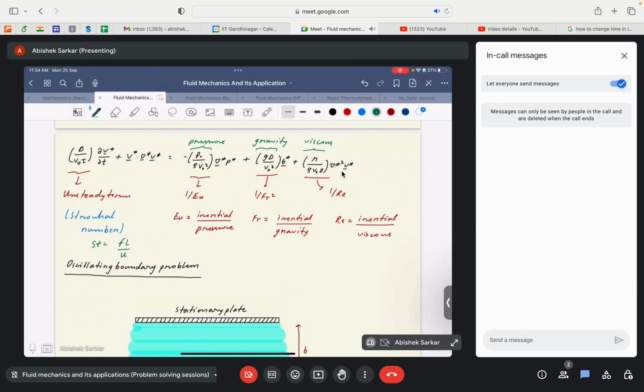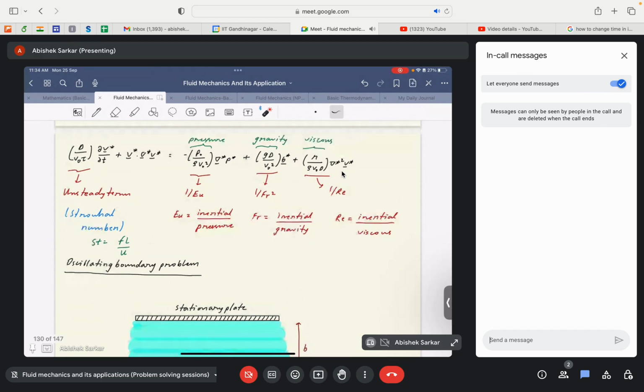But you can see here, instead of frequency, you have a time parameter, non-dimensional time. Since frequency is the inverse of the time period, you can ideally consider this tau as the time period of oscillation. That's the way to look at it. For the non-linear advective term, there is no coefficient; the coefficient is 1, so that's fine.